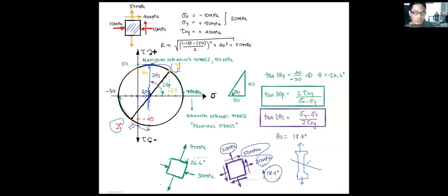45 degrees, right. Suppose we have a metal with the FCC structure. Which plane, which Miller indices, represents the close-packed plane? It's 111. So you know the slip process occurs in the close-packed plane and direction, and the angle is 45 degrees. I just want to make some connection between design and materials science.